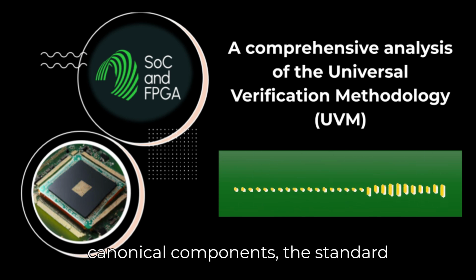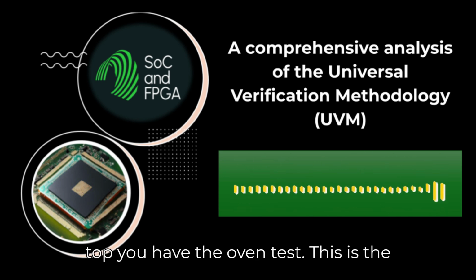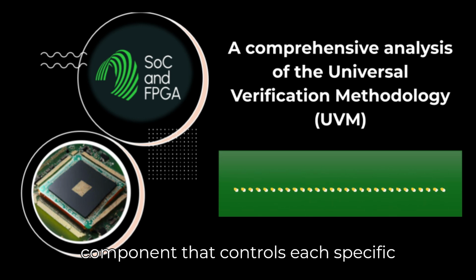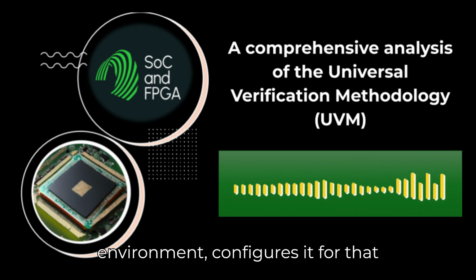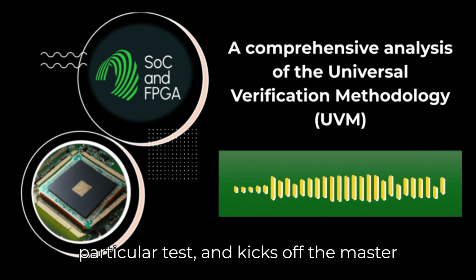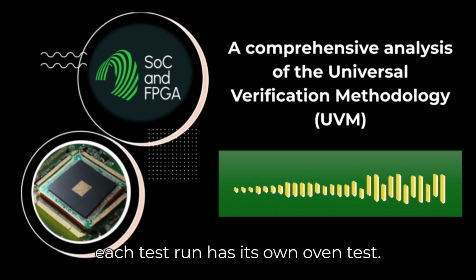So what are the canonical components, the standard building blocks everyone uses? At the very top, you have the UVM test. This is the component that controls each specific simulation run. It instantiates the main environment, configures it for that particular test, and kicks off the master sequence that generates the stimulus. So each test run has its own UVM test.